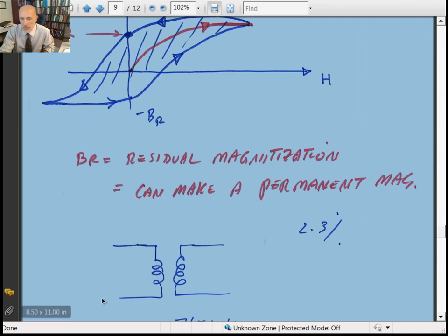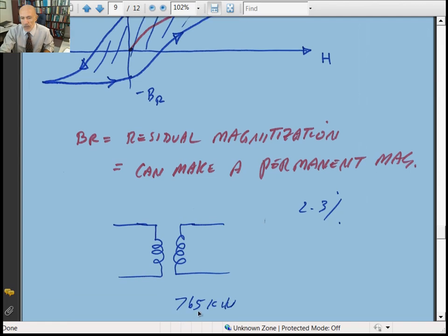Because if you're building the power transformers, they are three-phase. I'm looking at a single phase here. The voltage generated here is anywhere from 18,000 to 24,000 volts from your steam turbines that convert the potential energy or the kinetic energy, depending on what type of power plant you have, into electrical energy, which is about 24,000 volts maximum. But in order to reduce the transmission losses, the power company jacks the voltage up to about 765 kilovolts.